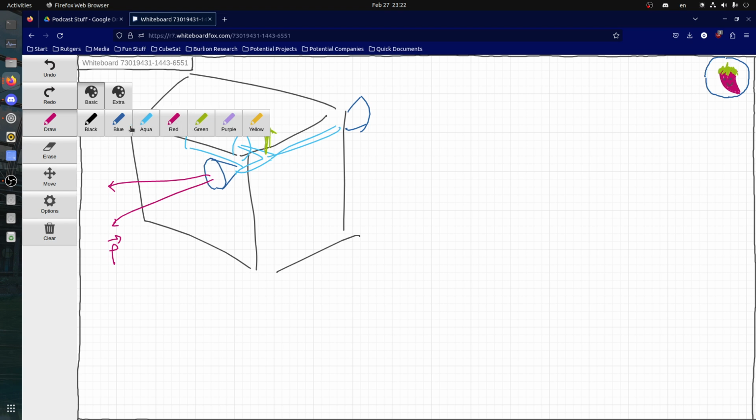Usually, there are more problems with these because if your reaction wheels aren't aligned perfectly, right? So in this case, let's say there's a small deviation, this will actually end up causing another torque. This little red over here is the deviation. So what will end up happening is if you fired both of these together, there would be a small moment. This one would have gas flying this way. This one would have gas flying this way. There'd be a net torque in that direction, right?